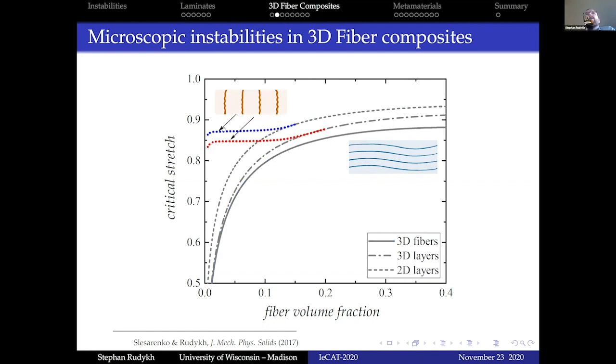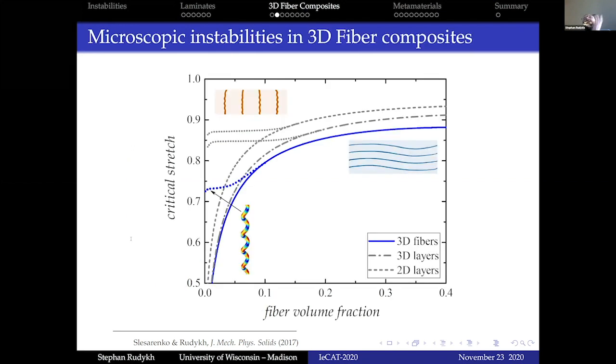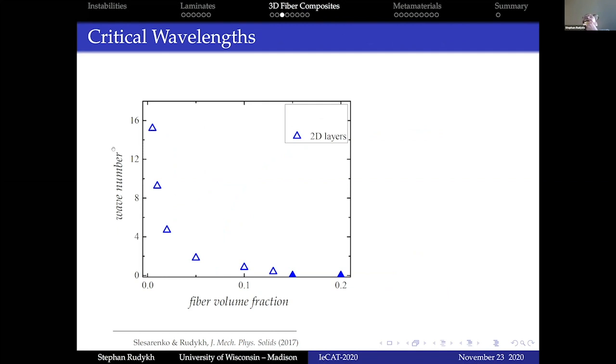So in that microscopic instability analysis, it uses the Bloch-Floquet analysis, where we scan different wave numbers. That nicely predicts the appearance of these instabilities also for laminates and for fibers. And for fibers, there is an interesting indication that maybe we'll be able to develop helical-like structures. So this is again to answer the question of what the critical strain or critical stretch is, basically answering when the buckling happens. And next I'll show the information on what actually happens at the microstructure length scales.